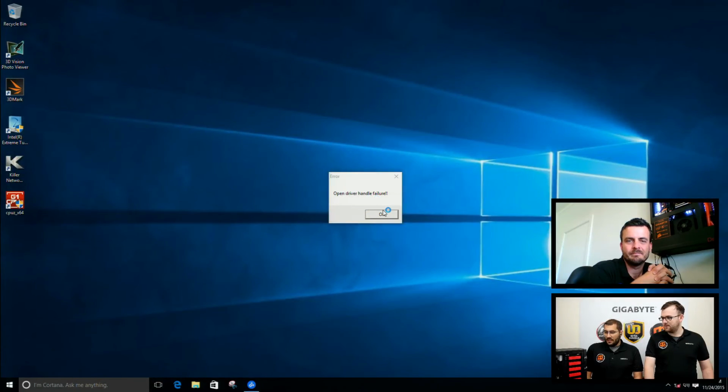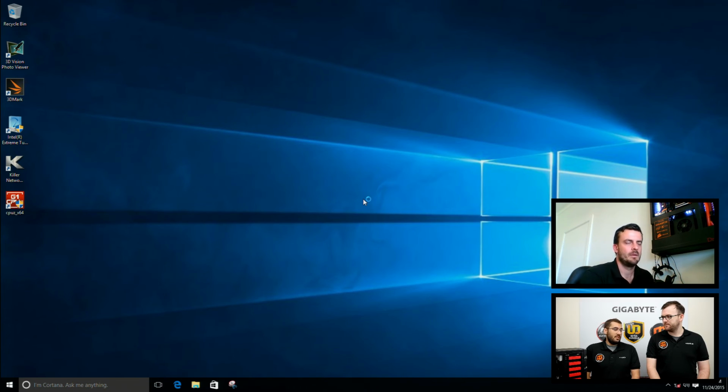If you want to overclock your PC again, because right now it's back to the stock frequencies, all you have to do is repeat what we saw before. Launch EasyTune, load your CPU settings, also your XMP profile, and you're ready to go. I just want to stress that when people are overclocking, they should first increase the voltage of the CPU. So we had it from 1.25 to 1.35, and then go in 100 megahertz increments on the CPU. Don't do big jumps, say 500 megahertz up, and see if it's going to work. You're better off doing small increments, then run a stress test. So go from say 4 gigahertz to 4.1, run the test, make sure it's stable, go to 4.2.